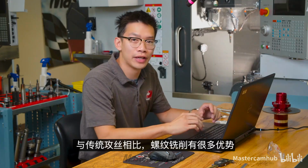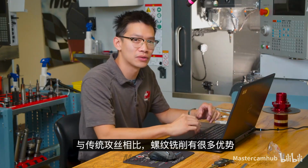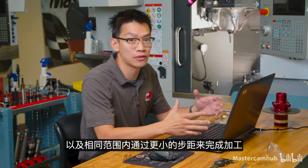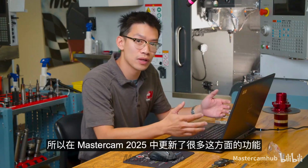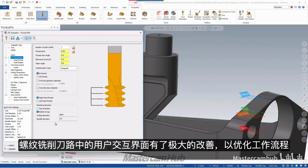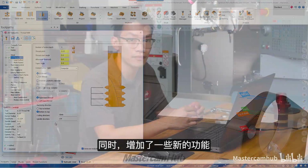Thread milling has a lot of advantages over traditional tapping cycles, such as better thread tolerances, better tool life in harder materials, and a need for fewer tools to cut the same range of hole sizes. Users have been asking for more advanced control over the lead moves for thread mill, so starting in Mastercam 2025, it's received numerous updates. The entire thread milling toolpath has been gone through and organized to improve the workflow, along with adding some new features.